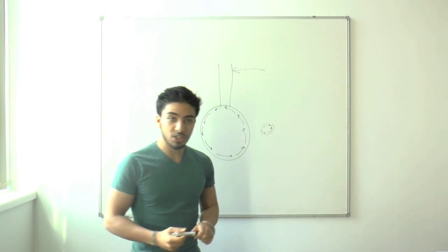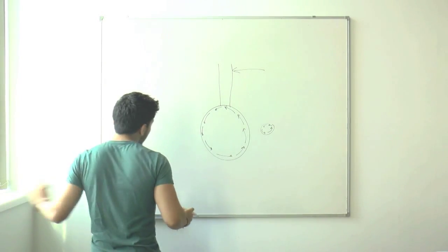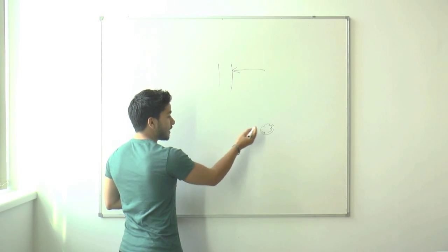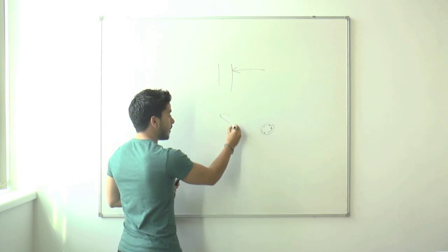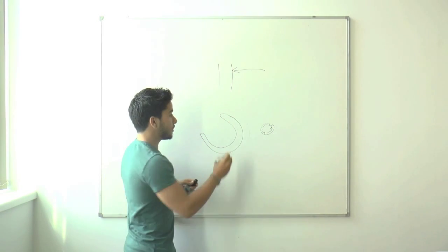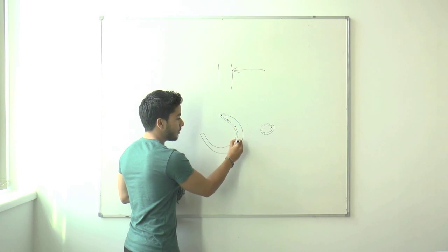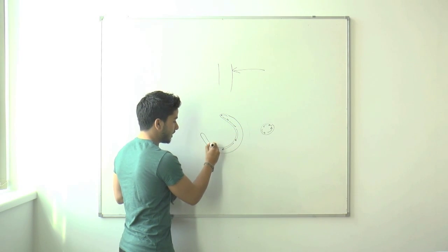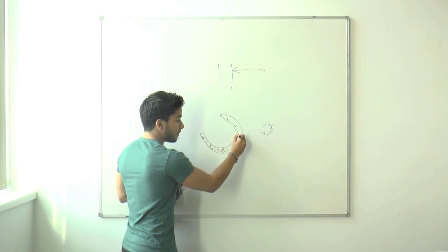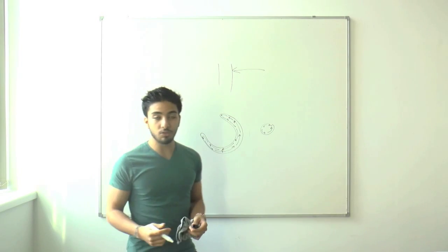Alright, to explain this, we're going to draw another illustration. If we have, as opposed to a closed section, an open section, what the shear force is going to do is, because it's limited, it's going to form a much narrower loop, because it has less material to occupy, and that is why it has less resistance towards torsion.